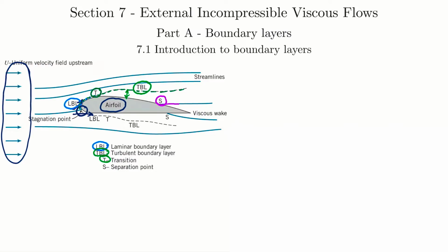So they've got this solid line shown here now. So the flow separates, it means it no longer stays against the wing here. So where you have flow here at the separation point now, that separates, moves away from the wing, right? And then you have another separation point shown at the bottom here. So the flow moves along here and the flow moves along here at the top, right? So the flow's moving here and here. And then within that region, you're creating a viscous wake, which shows up like a turbulent wake behind these objects.